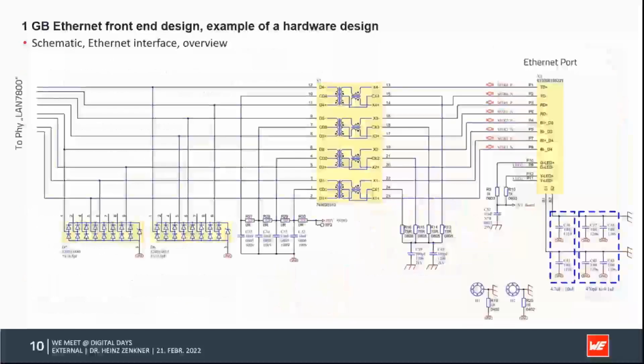We have the cable connected, and all, let's call it, transient voltages and transient currents, which are induced or impacted on the cable due to bursts, surges, or RF voltages regarding EMC immunity, are converted in the transformer into common mode, meaning on the secondary side you will have common mode disturbances on all channels.